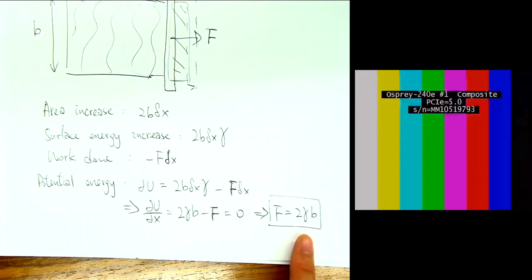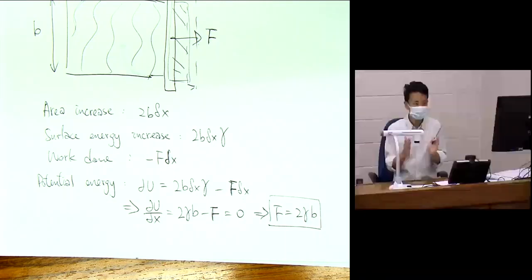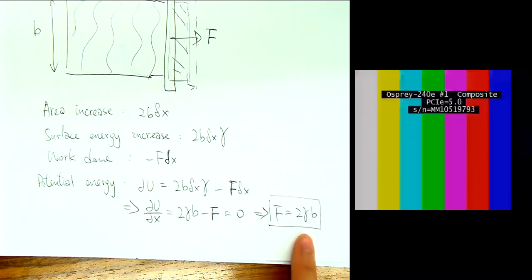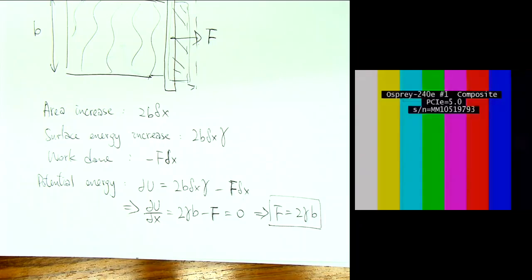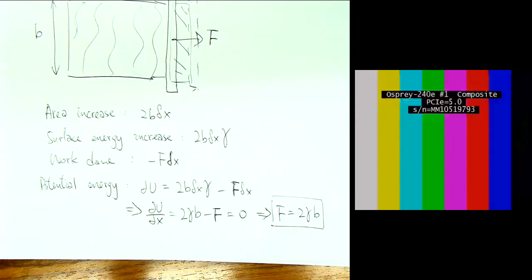Okay? So you see why it always breaks. It's very hard to control, because if there's only one surface energy, there's only one force you apply, and the whole thing is going to be in equilibrium. If you slightly increase that force, let's say that you jerk your hand, okay, a slightly higher force is being applied. Surface energy does not increase because that's the property of the film.